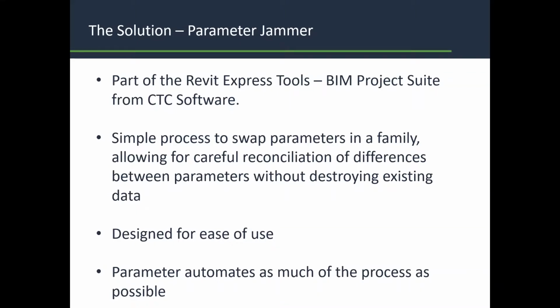As I mentioned before, it's designed to be very easy to use. You do not need to know anything about Revit families to be able to use this tool, because it automates most of the process for you. You just select the schedule you want, select the family that you're trying to push these parameters to, and how you want them pushed, and then hit OK, and you're good to go.